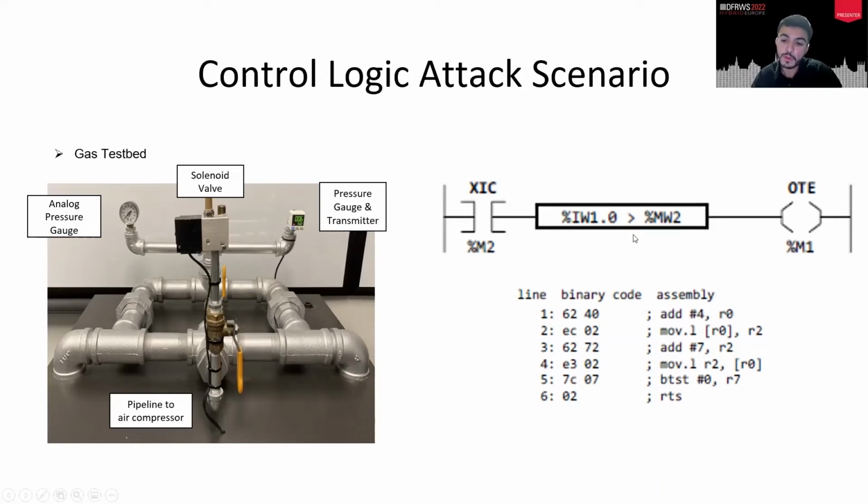Before, we wrote malicious code for the timer instruction; now we wrote it for the comparison instruction. What it does is, it always sets the output to true, because it never does a comparison because of the malicious code, and it's always on.